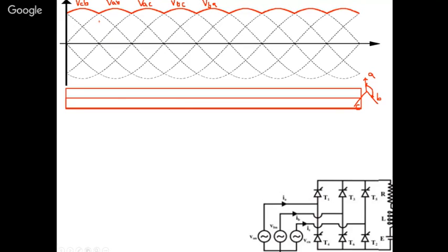So I've drawn this switching, and here in this case, first initially zero switching, in the sense our T1 will be fired here, T2 here, and T3 here. So this is zero switching. In the sense you are switching at that instant, like the zero crossing of two phases. Like how will we choose this? In case of a phase voltage, say you are doing it practically, what you will do, you use a zero crossing detector. Okay, and you will just see that when two phases cross each other.